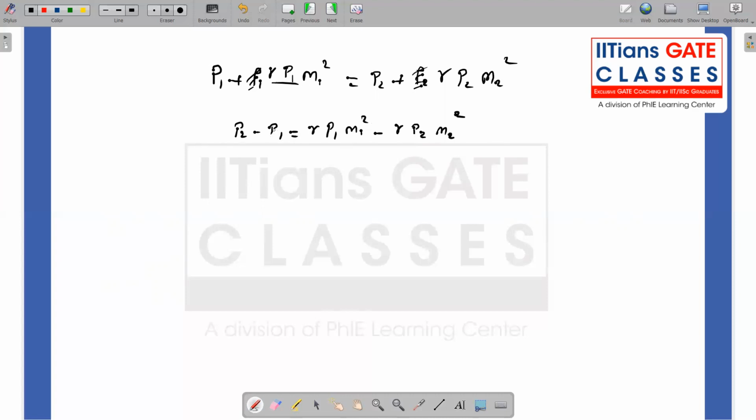So now if I take P1 common from both sides, it happens P1 times P2 by P1 minus 1, which is also equal to gamma P1 times M1 square minus P2 by P1 times M2 square. So from both sides P1 can get cancelled. So now I can write it for P2 by P1 because here also I have P2 by P1, here also I have P2 by P1.